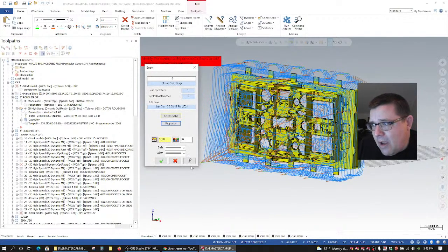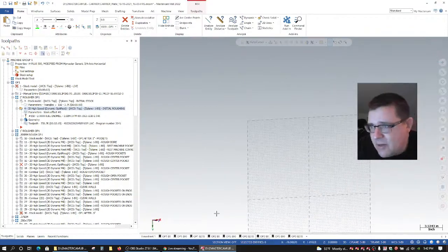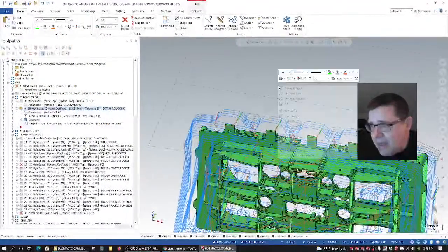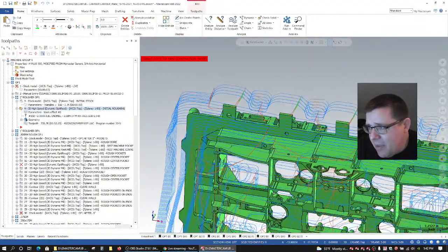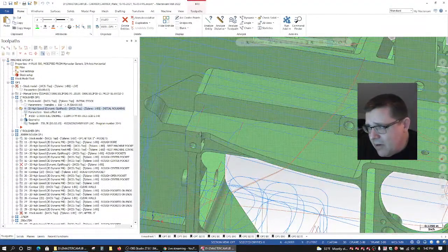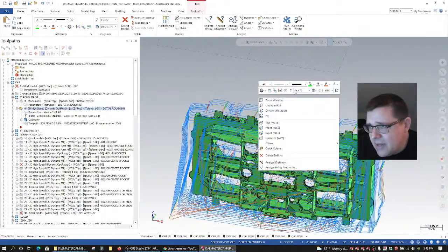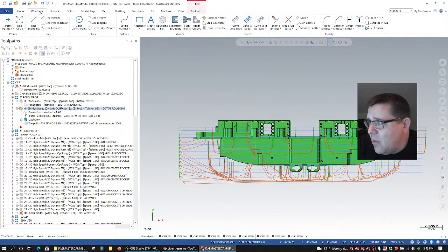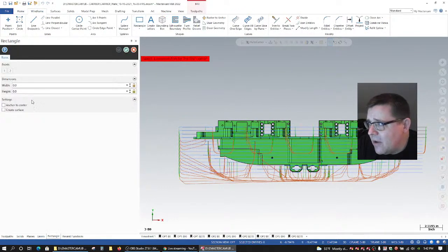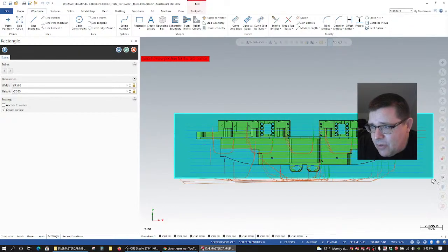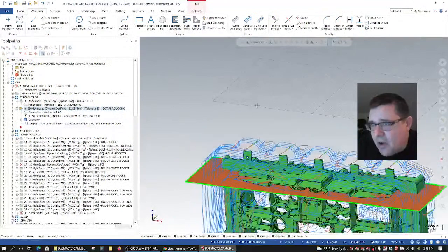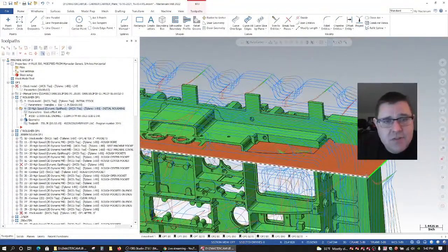And what I typically call that, so for example, if I look at this in the top view, and I select a depth down here, so that's 13.42. And I go to my wireframe, rectangle, create surface. I will often do something like this that I like to call a run-out surface.